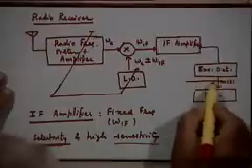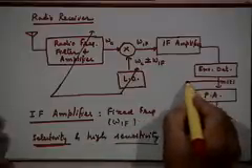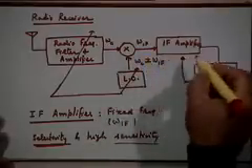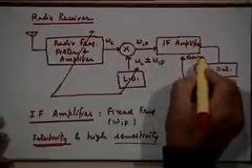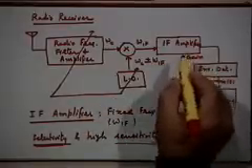So there are other things that you require in the receiver. For example, there should be some mechanism to automatically control the gain depending on whether the incoming signal is weak or strong, right? Typically that is done by taking a feedback from here, by looking at the message signal and seeing how strong it is, and using that feedback to modify the gain of this amplifier. So there is a gain control signal which is generated through some processing. The IF amplifier gain is reduced or increased depending on whether you are working with a weak signal or a strong signal.